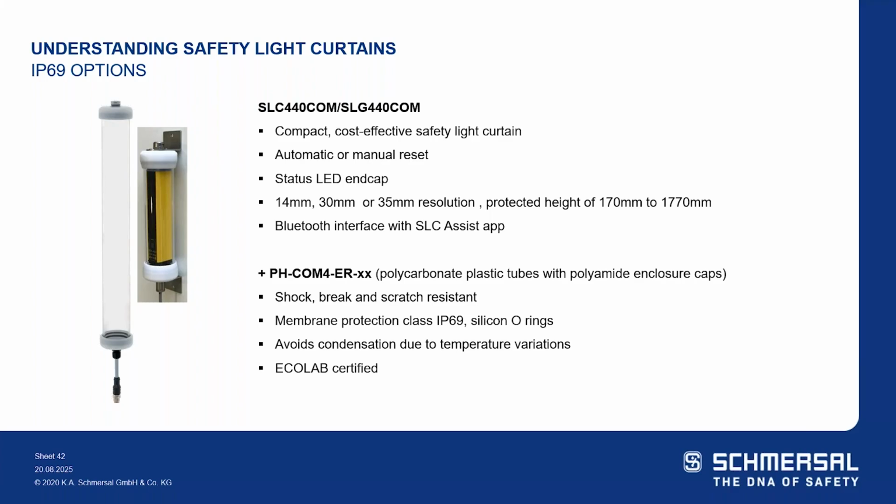So both the light curtain and the light grid will allow for an IP69 protective enclosure. Again, Ecolab certified. Ecolab certified means that a third-party lab has tested our devices to, I think it's 5 or 6 typical cleaning agents that are either acidic-based or alkaline-based, and they can withstand those readily available cleaning agents.